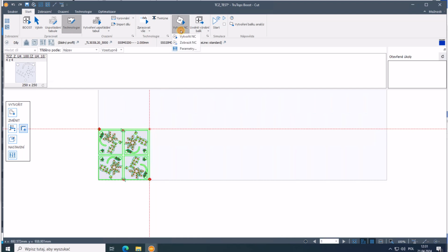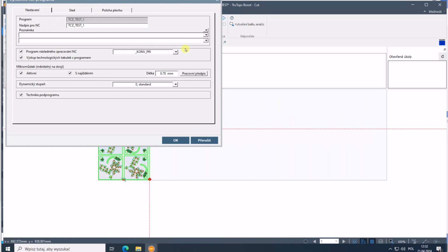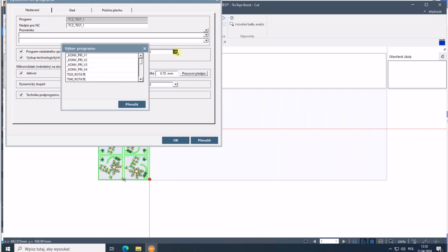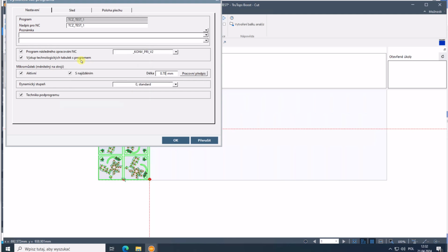In this mode I can edit my parameters of calling my NC programs, and before I prepare the NC file for the old job, I simply said I would like to vaporize all piercing points in the part, and I would like to do it partwise. It's the second method of the vaporization of the conversion application. Press OK.